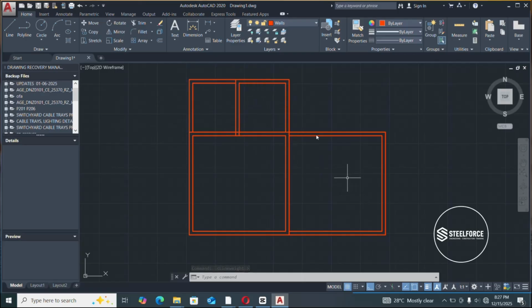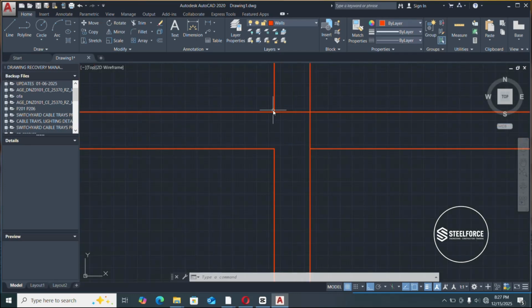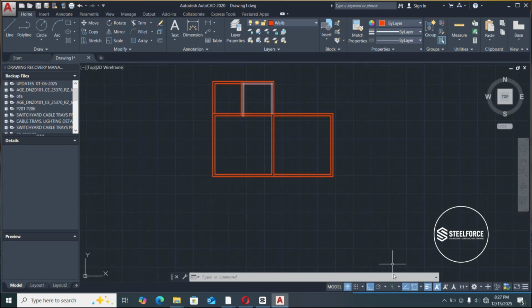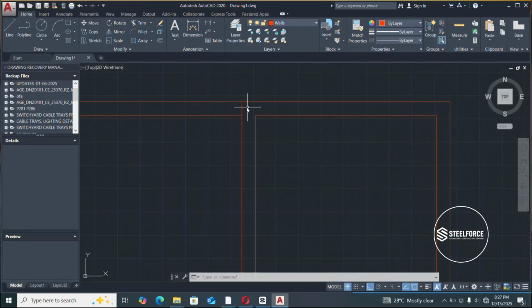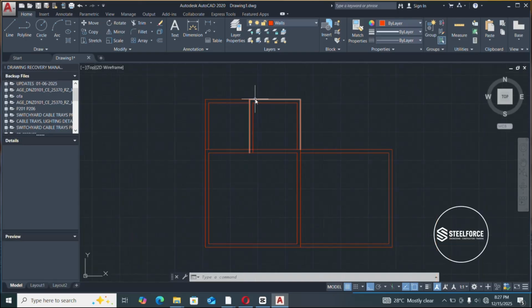But sometimes when the lines become this thick, you find it difficult to select the lines, or you don't see if the lines have met. So you can just turn it off. After you are done with your drawings and everything, then you turn it back on. So you realize that there are some lines exceeding, so we have to trim. You either type trim TR on the keyboard, or better still, you just select trim from here.